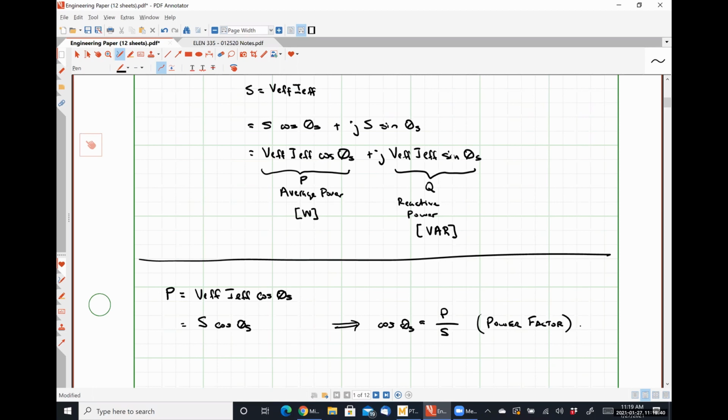And the reason why that happens is because if we determine the instantaneous power for a capacitor or for an inductor, the DC portion, the average power, is 0. So what that means is that in capacitors and inductors, every cycle that power is sent to that element, half of the time it is being absorbed, and the other half of the time it is being sent back to the source. So it's absorbing and sending back over and over and over. It's never actually doing any work whatsoever, just being transmitted, being sent back.